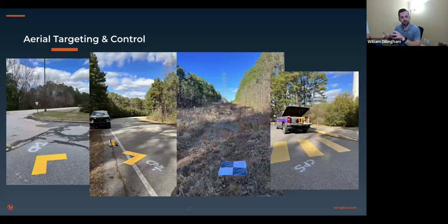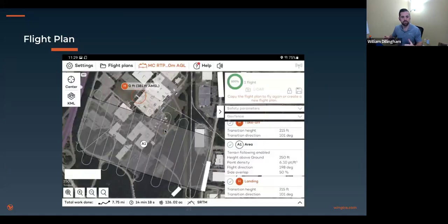A second type of calibration that happens is an automated calibration. This is done with a trajectory processing software. Inertial Explorer, NovAtel's wonderful processing suite, is used inside of the Wingtra LiDAR app for processing the point clouds. When the drone first gets put on the ground with the payload inside, you do a static alignment where Inertial Explorer measures some initial biases of the inertial drift.